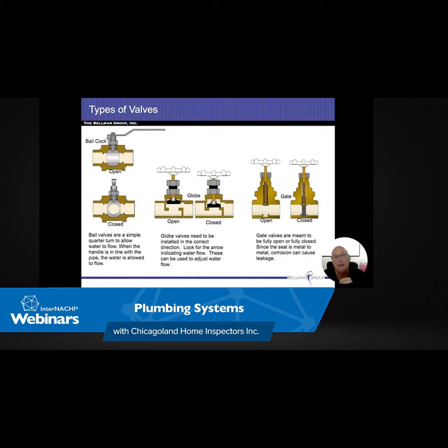All right. Here we're showing different types of features or different types of ways to make those traps. I'm not a big fan of gluing a trap and making it permanent. I do like those screw fittings so you can take it off. If somebody does drop something in there and it gets caught at the bottom of that trap, simply unscrewing it, we could go ahead and find it at least. Otherwise, we're cutting pipes, damaging them, and then we have to repair everything when we come back in there. But it's still not the end of the world. I just want my clients to know if it's fixable or not fixable.